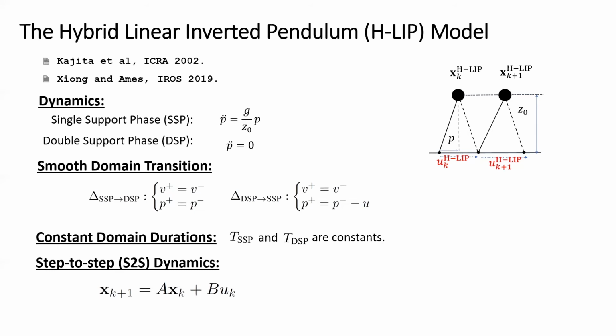One should note that the H-LIP is used to approximate the walking. The walking itself does not have to be of constant center of mass height. The double support velocity does not need to be constant. Those will produce the model difference.